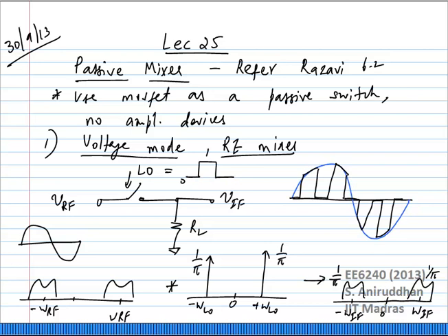Of course, the assumption is that IF is much smaller than LO. In a receive mixer, that is absolutely true. What you're saying is right, because we can choose to not look at the fundamentals. We can choose to look at some nth harmonic of the LO, mix that with RF and use that translation as our desired frequency. The only thing is we'll get a much smaller amplitude at the output, so the conversion gain will be very small.